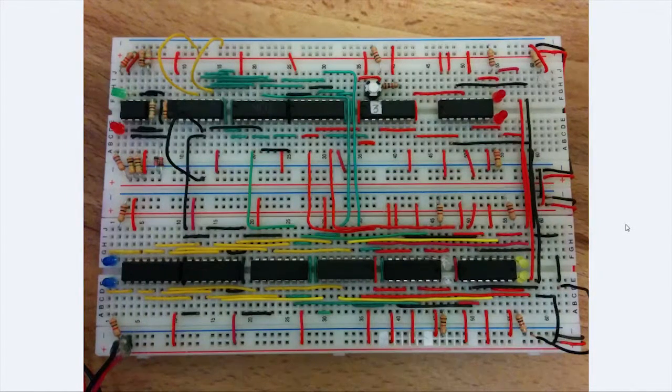First off, what is a memory circuit? Well, a memory circuit is a group of registers called memory locations that allows storage of one multi-bit binary number, also known as words. A memory circuit is often used to store certain data at desired locations. Since mine is a 3x2 memory circuit, it can store 3 words that are 2 bits long each.